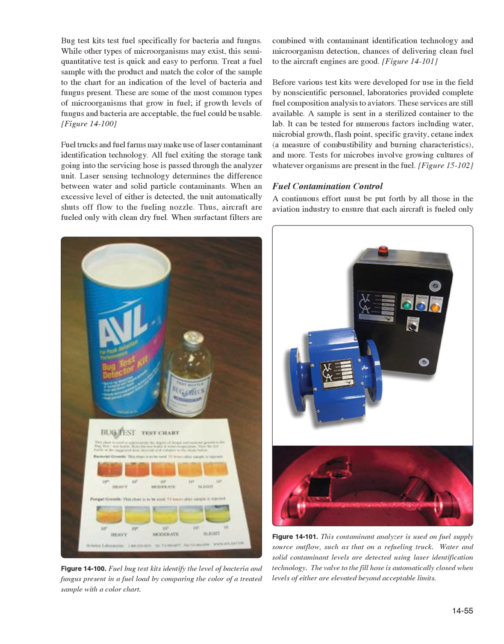Figure 14-100. Fuel trucks and fuel farms may make use of laser contaminant identification technology. All fuel exiting the storage tank going into the servicing hose is passed through the analyzer unit. Laser sensing technology determines the difference between water and solid particle contaminants. When an excessive level of either is detected, the unit automatically shuts off flow to the fueling nozzle. Thus, aircraft are fueled only with clean dry fuel.